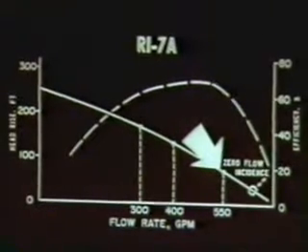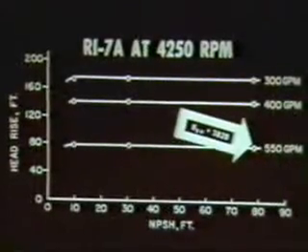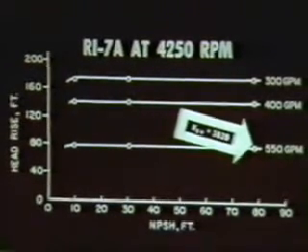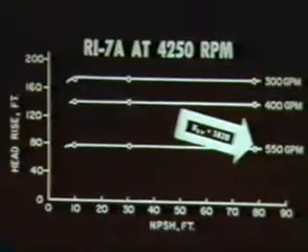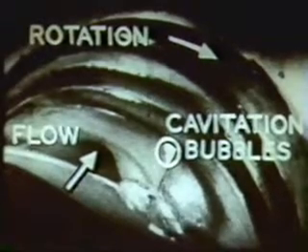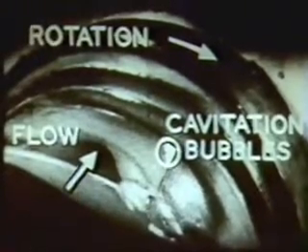Note that these operating points were all at positive flow incidence. The cavitation is localized on the suction surface near the tip leading edge of the impeller vanes.